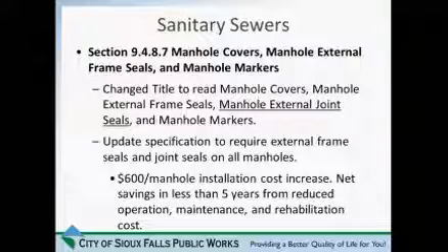Previous to this, external frame seals were not required on all manholes, just in our drainage areas. Now they will be required again on all manholes, and our joint seals. I have a couple pictures of what they are on the next slide. First, I want to mention we expect the cost of these to be approximately $600 per manhole, assuming an average manhole depth of 8 to 12 feet. We expect the net savings to be recouped in about 5 years just from the reduction of maintenance and rehabilitation cost. So we feel that this is a necessary thing to save cost in the long run.